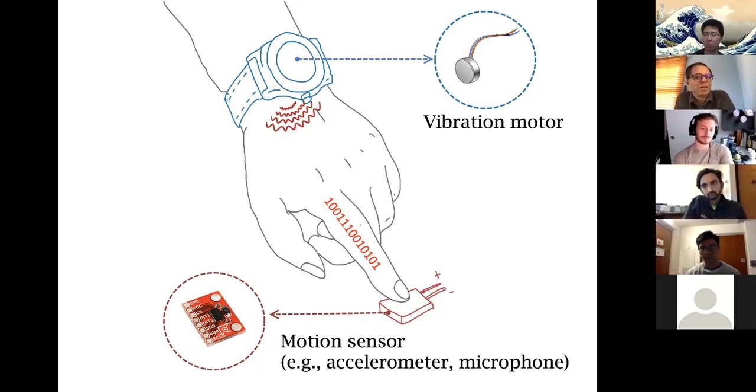If you see that with 20 hertz bins the noise characteristics of your accelerometer and your vibration motor are too high, maybe you want to increase the bin length because you want to average out noise. Now you do engineering, but you see what the idea is. Any other questions?